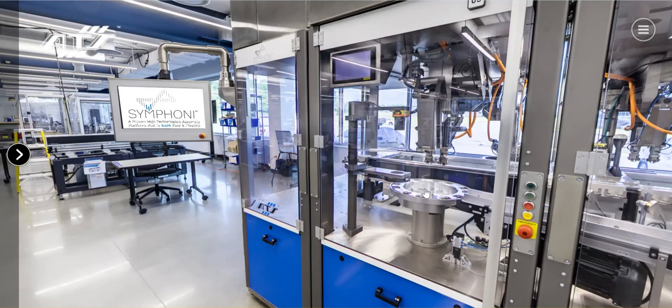But through the HMI, you can do things such as select different types of profiles, adjust pick and place points. Should that be required, you can make adjustments in pallet positions in 0.01 millimeter increments, etc. Another thing that you can do from the HMI is select what rate you want to run at. One of the characteristics of Symphoni is that it operates in a synchronous fashion.